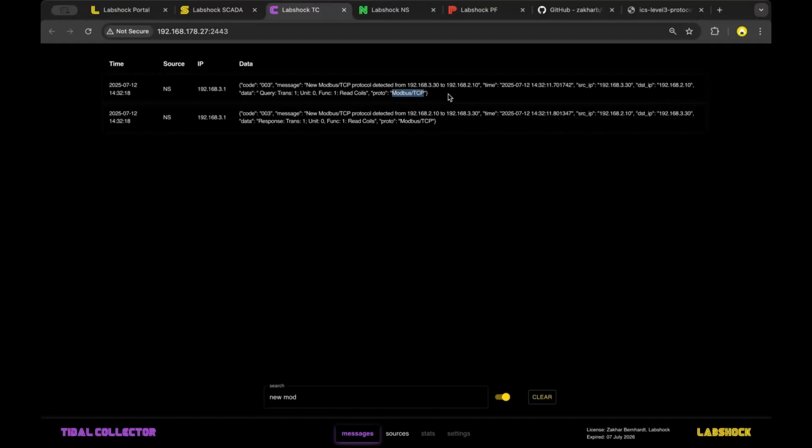And after that, of course, you need to protect first. Maybe we are switching a little bit to how to protect from this Modbus. The first thing is you need to segment your network and, of course, protect your switches from unauthorized access of different devices that are created inside your process level 2, level 1, or level 3 networks, to not give this possibility to communicate with PLCs.